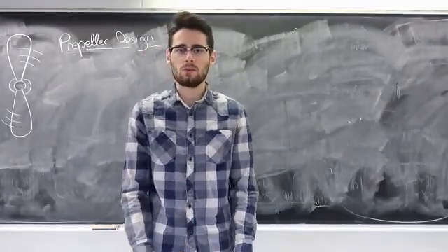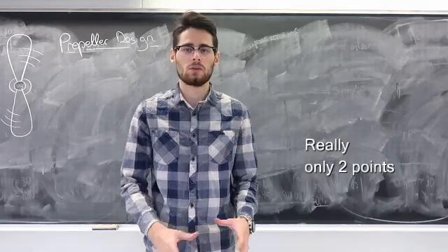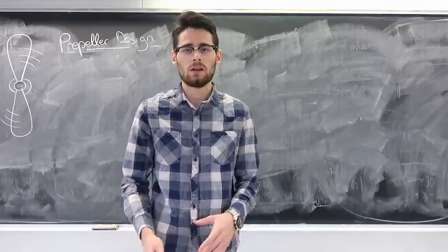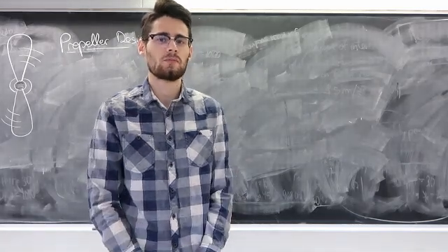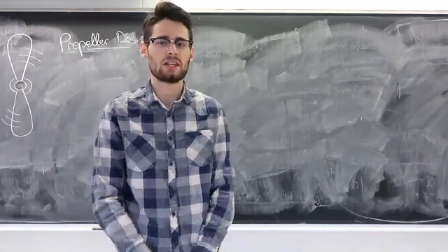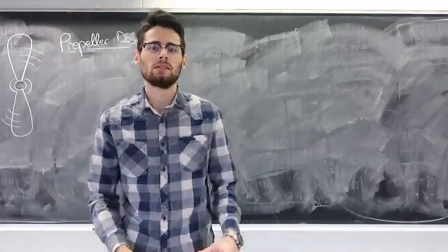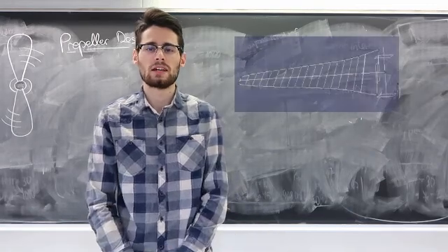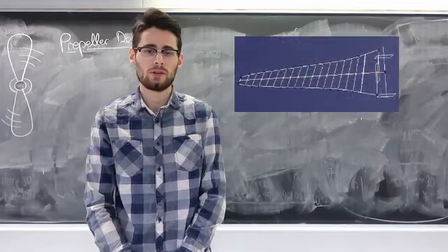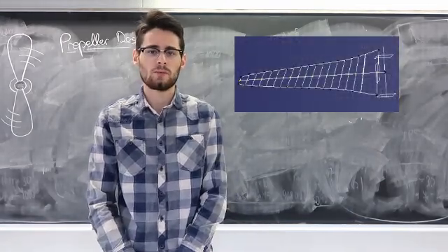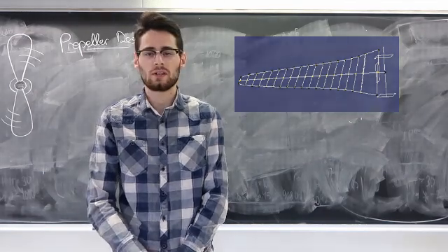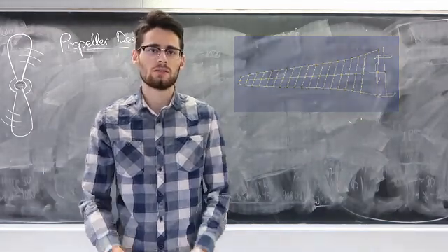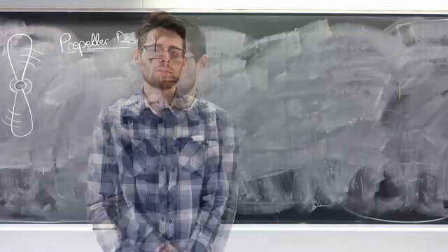There are 3 main points that are important: the joint from the propeller to the hub, and the end of the propeller. The calculations only give us the chords from 50% of span to 95% of span. To get the tip of the propeller, we decided to have a taper ratio of 1/3. And to connect the propeller to the hub, we decided to do an extrapolation of the calculations so that we can join the propeller to the hub.